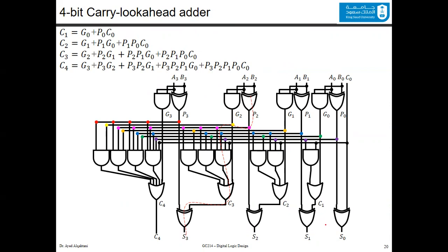You can see that the sum doesn't have any trouble for the carry look-ahead addition, because now this sum is the XOR with another XOR. So it's 3 input XORs that generate the sum. Same idea in the ripple adder. Similarly, for this sum, it's the XOR between this and this, XOR and XOR. So you get the carry XORed with A and B XORed with the carry, and so on here, and here, and here.